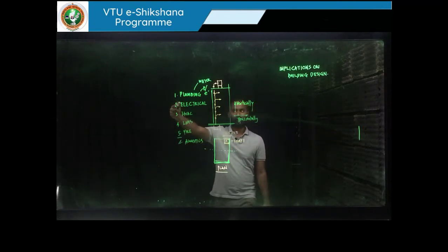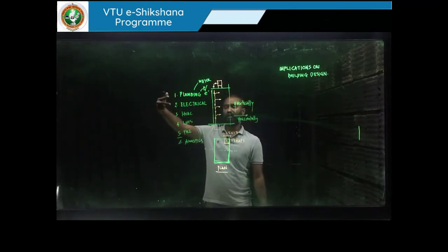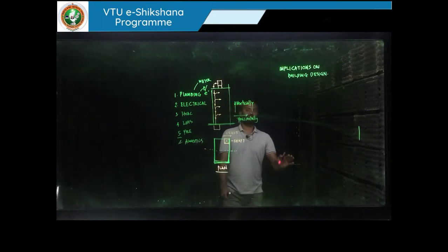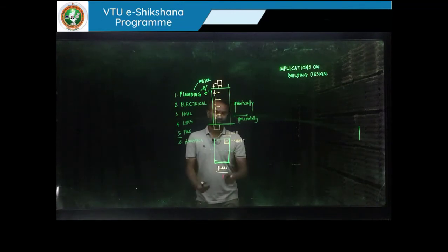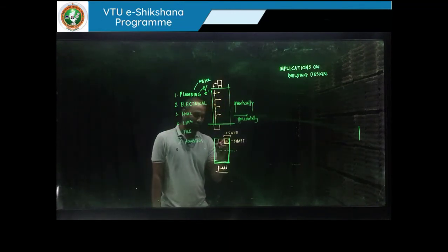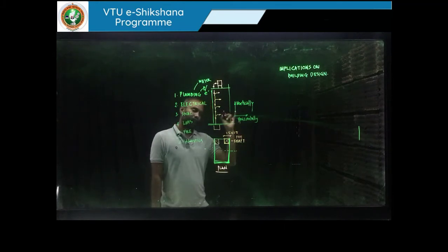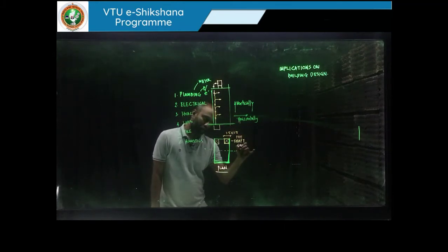If you allow them to interact, all these guys within themselves, it is going to be a disaster. So we are not going to let that happen. We will tell them where and how it has to be done. A simple way to solve this problem is to have a couple of shafts. Of course, it is going to be through the shaft arrangement, but we are going to call this the plumbing or public health engineering shaft, where it is going to have only water movement, right?